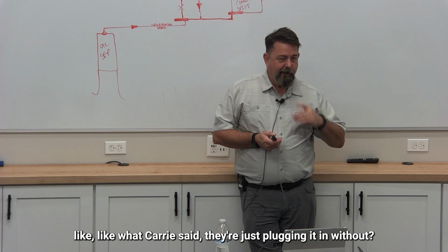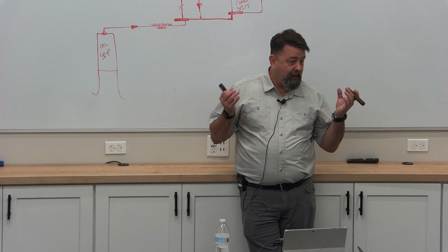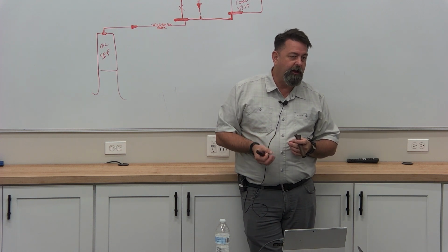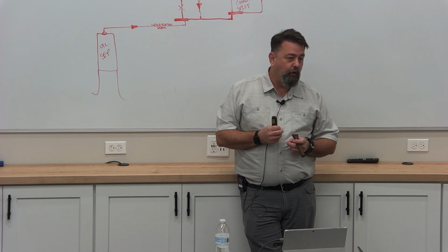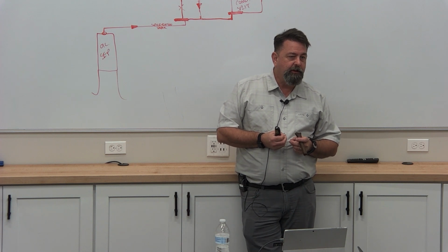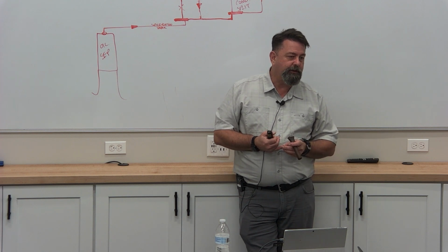What Carrie said, they're just plugging it in without? No, they're running the case, right? So they are running the case in a laboratory environment. They're running it at 75 degrees, 55% humidity. They're putting the shelves on this thing. They are stocking it with bottles of water, letting those bottles of water make core temp, get below 41 degrees, right? And then they're gonna take this reading immediately after defrost.